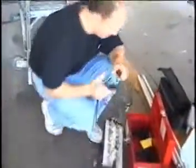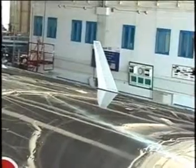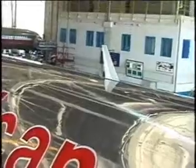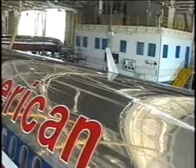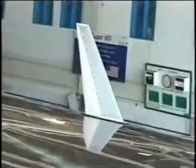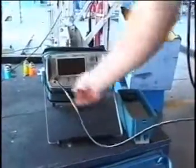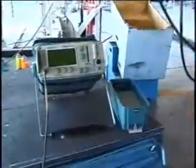When preparing to test a cable, consult the wire list and note the cable's length and impedance. Keep in mind that you never connect the live cable to the tester. Always disconnect any transmitter from the cable to be tested, and if the cable terminates at an antenna, ensure this antenna is not receiving a strong signal at its tuned frequency. Be aware of walkie-talkies and other transmitters in the area that can be picked up by the antenna and cause damage to the tester. Bleed the cable to be tested and any adapter cables before connecting them to the tester, and connect cables to the TDR through a static suppressor when available.